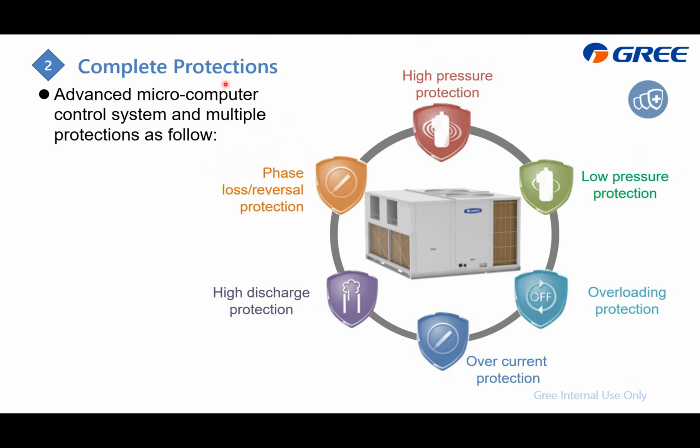Complete protection. That means during the design stage, we already considered malfunctions, including for the refrigerant, which is the high pressure and the low pressure. And also we consider the power consumption, which is the overloading and also the overcurrent. That indicates that something is wrong with the system. When we detect that, we will trigger the error, and this can ensure the system reliability and also the lifespan. And this protection is also right inside the microcomputer chip.